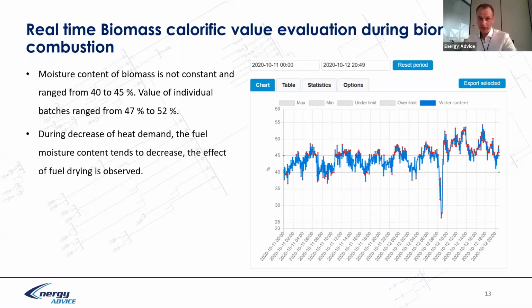It's a very interesting question, and maybe your question is, can we reduce the supply temperature of the water, or should we increase the supply water temperature? But in fact, this should be according to the dew point of the flue gas, and this would be according to the water content in the fuel. So the optimization would be related to this.